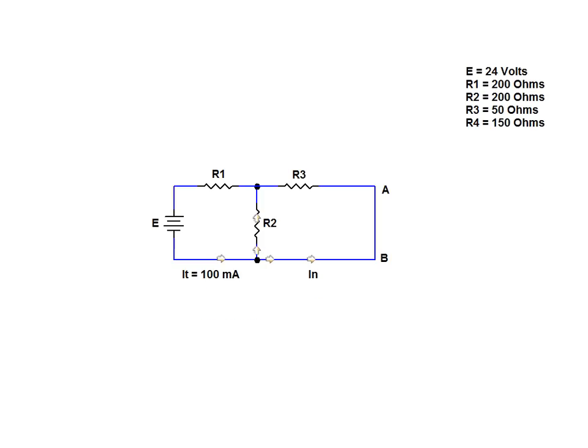Once we have determined the total current flowing in the circuit, we use the current divider rule to calculate the Norton equivalent current. This current flows through R3 as well as through points A and B. The Norton equivalent current, IN, for this sample network is equal to 80 milliamps.